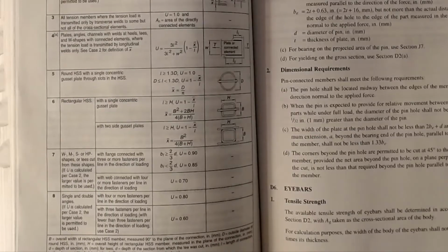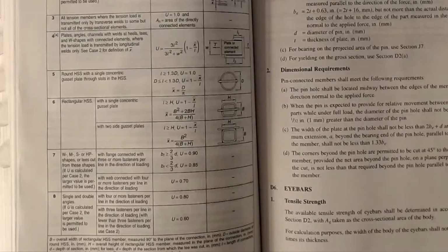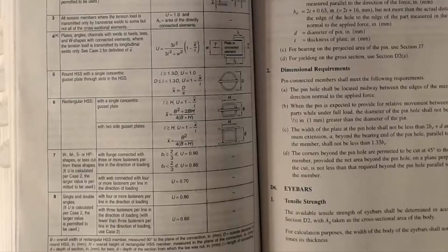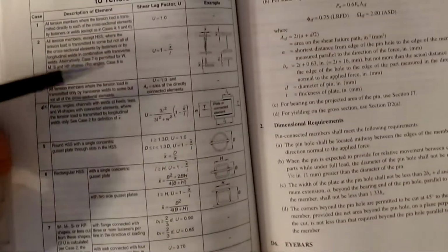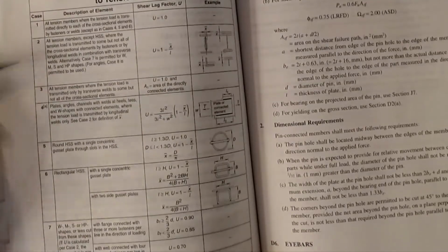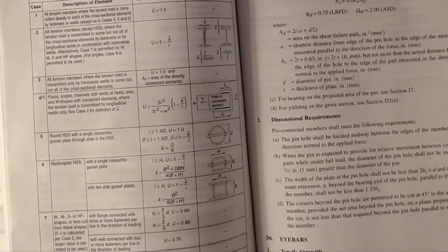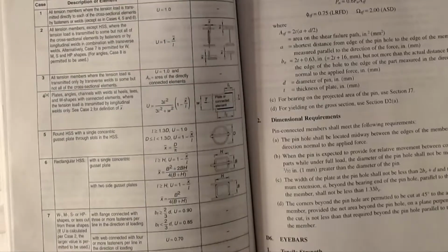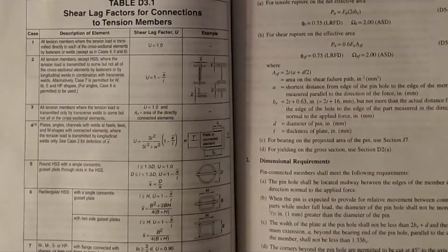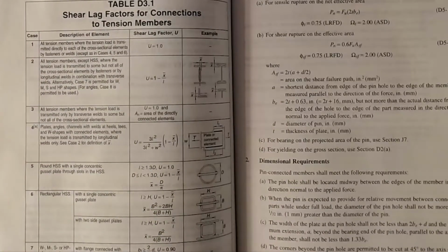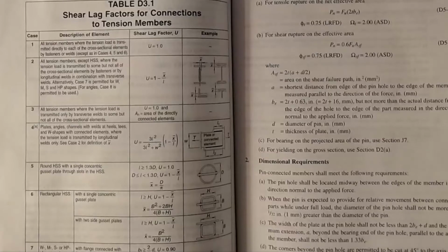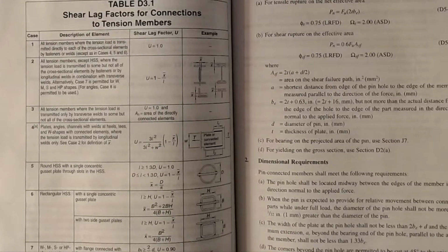But once you've got your configuration laid out, your connection determines bolt spacings and the gauge distances and all that determined, you're better off coming back up to case 2 and checking that value that we had up here. So this is kind of the catch-all version. If none of the other cases apply, you're in case 2 for computing these particular values. All right, so that's kind of how table D3.1 works. You've got to be very careful in what you're reading and make sure that you're catching all of the key words, like "some but not all" or "directly to each" of the elements. Those are all the key words that you're looking for in this table.